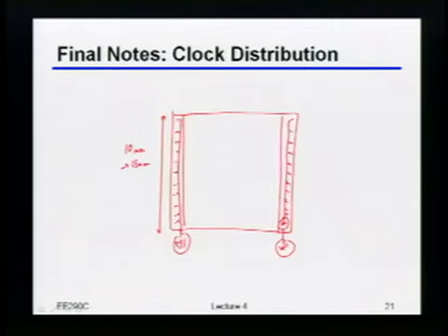Now you can imagine that with both of these, you have to be really careful with how you distribute those clocks. Because to cover about 10 or 15 millimeters, you're going to pick up a lot of loss, even at the lower frequency of the crystal. That means you probably have to insert some buffers. Well, guess what? Those buffers usually are sensitive to the power supply, so you'll very easily pick up quite a bit of jitter just from distributing that clock across that distance.